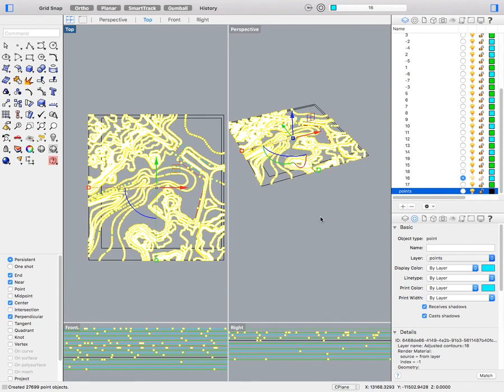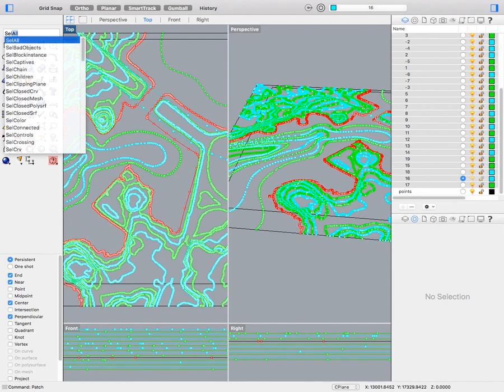What does that command do? It's taking basically all of the control points on each of your curves. It just takes those points and extracts them so they're not technically associated with the line. You could do it both ways and just turn on the control points and use those control points for the next command. But I just find it easier to extract those points and put them on a new layer so that we can separate the geometries when we're making them. Okay, so select.